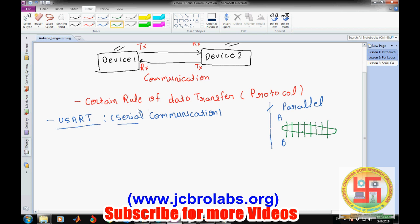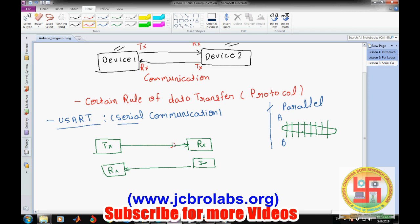Now in case of serial communication, from a transmitter to a receiver, or we can say from one device to another device, we have a single wire. And if it is a transmitter and it is a receiver, we have another single wire. We are transmitting data over this single wire, which means we can't send in parallel, we will send one bit at a time. So if we are transmitting 8 bits of data, then we are transmitting 1 bit at a time to the devices. That is why it is known as serial communication, because we are transmitting the data serially, 1 bit at a time.